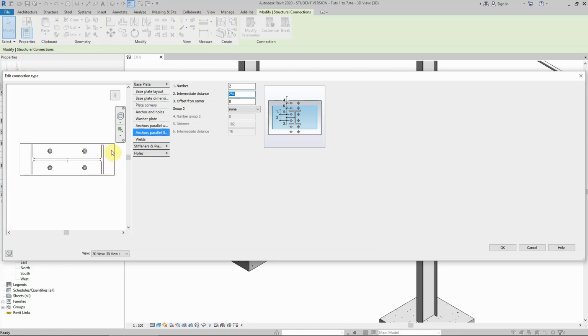If you remember, I will have my ports here at 35 millimeters, and that will allow another 35. I will have the flange thickness, and then if I can have another 35 or 40 millimeters, that'll be great. Sorry, I'll say it again. We have 40 because we chose this as 80, 40 millimeter each side of the bolts, and then the flange thickness, then 40 millimeter that way. It will be clearer after I finish the design.